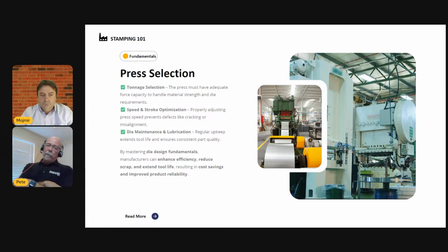Think about this. If a guide pin, or a leader pin, you may refer to it as a leader pin, could align the upper ram to the lower die, why doesn't the press manufacturer use leader pins to guide the press rams? Why such a complex gibbing system? It's because it's not sufficient. Leader pins, guide pins will deflect. And so you can put large pins in your die and the press is still going to deflect them. That is not the solution. Proper press maintenance is the solution.